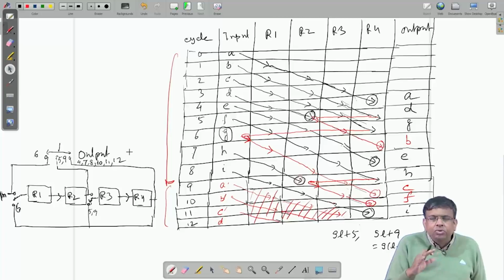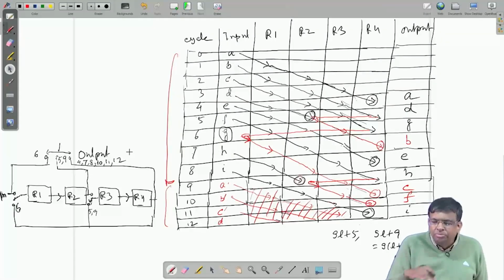So this gives you a fairly good idea about how to carry out the lifetime chart after doing lifetime analysis, and once you do the lifetime chart, you know the minimum number of registers required. Then you follow this forward backward data allocation table, this method of moving the data and still storing them in the system, and develop a circuit for it. This is the whole journey for minimizing the number of delay registers, because I am always hitting on the minimum number of delay registers required. That is why delay is optimized.